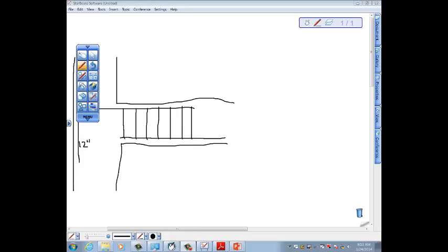I didn't print the other side, but I want you to go ahead and, right now we're looking at an elevation of this beam. So, oops, wrong way. I want you to draw a cross section of the beam to scale. Remember, it tells you the size of it up at the top. It says it's 10 inches by 18 inches deep. So this will be a section of this beam. This is my section. Whoops. I didn't want to do that. This is my section line.